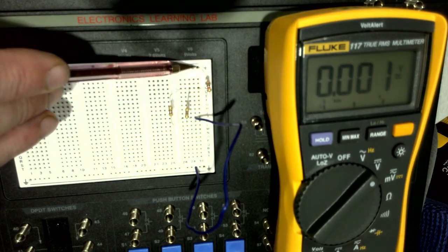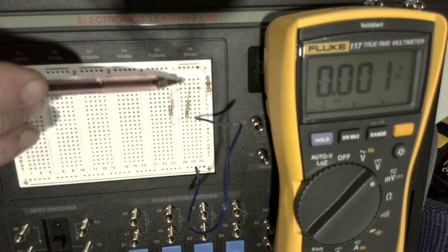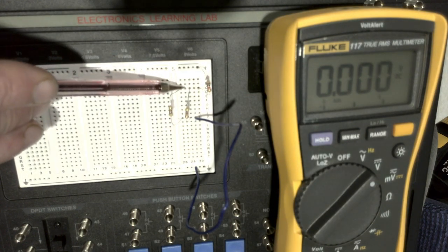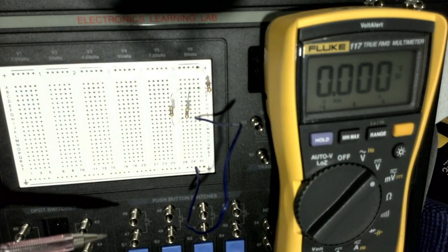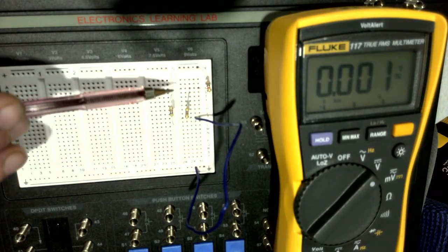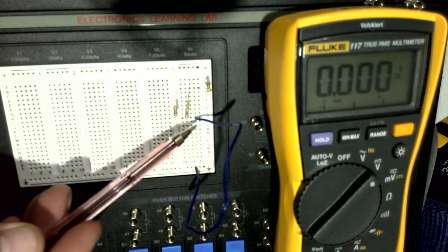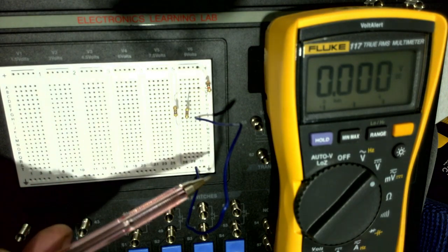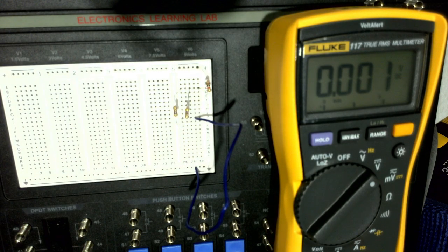So it goes from the positive terminal through this 1000 ohm resistor, and then all of these are connected. Every row is connected, but down the line, it's not connected. So then I go through the two parallel 470 ohm resistors. That's connected to a wire here, which then jumps those leads to ground. So that's how that relates to this.